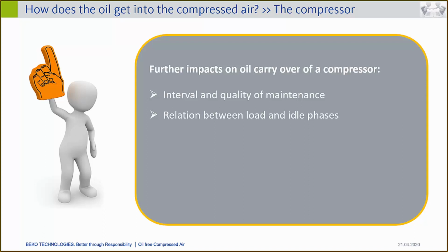Besides the compressor itself, the location is very important. So what's the ventilation of the compressor room? If there's poor ventilation, it has a negative impact on the temperature of all components, and that also leads to the compression end temperature. If there's worse ventilation, it has a problem with suction pressure. That is one point. So the performance of the compressor will get lower, or the energy consumption will increase. But if there's poor ventilation, I also have an increase of the end temperature.